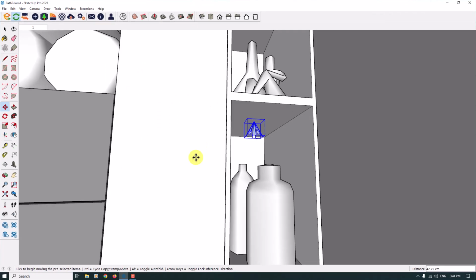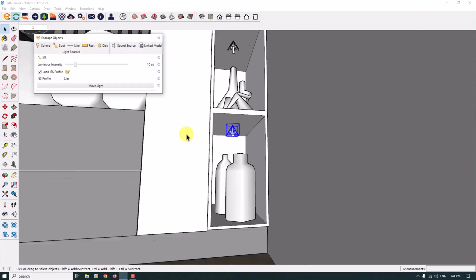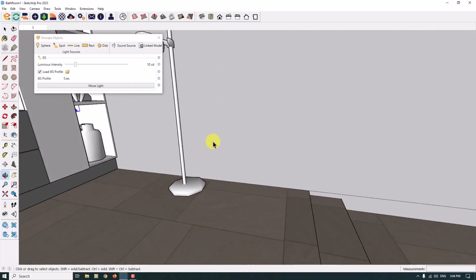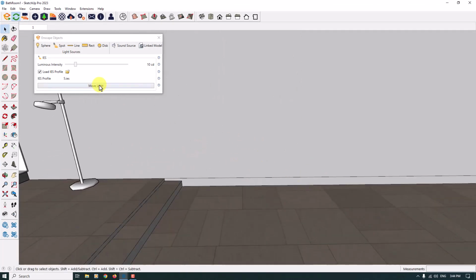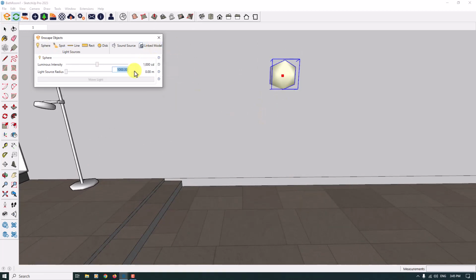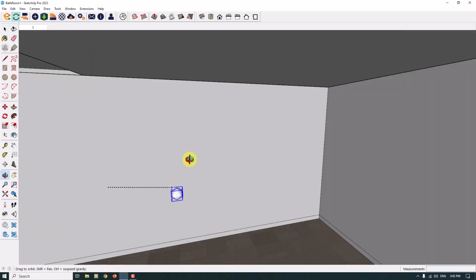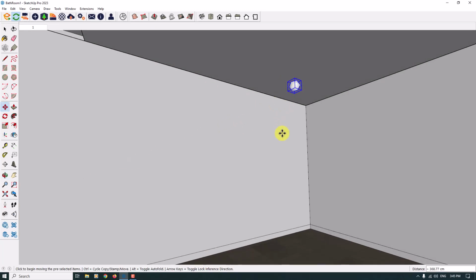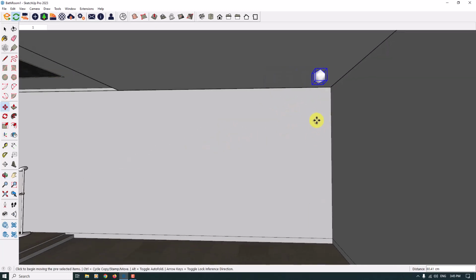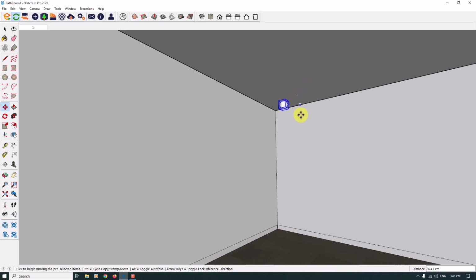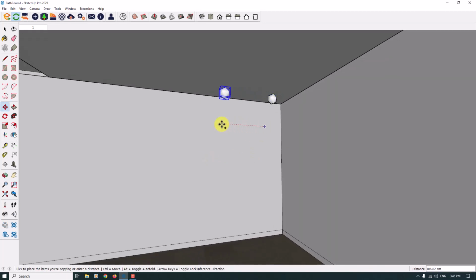So I'm going to close the Enscape. I'm going to save my job again and click on the Enscape object, and I want to create some sphere lights behind my camera. So I'm going to click on the sphere light and double click in my environment. So some number about 150 can be really useful. So I'm going to move it in this place and move it a little bit backward, a little bit to the left side, and take some copies at different distances.